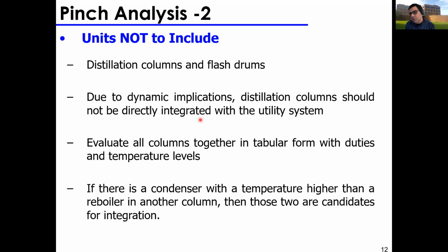Heat exchanger, if your inlet stream changes by a few degrees, your outlet stream is going to change by a few degrees. It's fine. Usually it can be tolerated in a process without any major issues, as long as you don't have a crossover in your temperatures, okay? But anyways, the bottom line is forget about distillation columns and flash drums when doing the initial pinch analysis of your process.